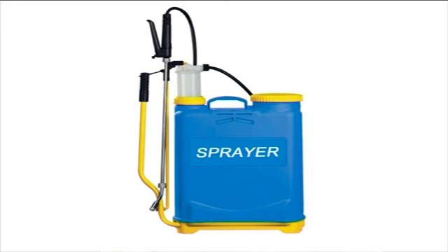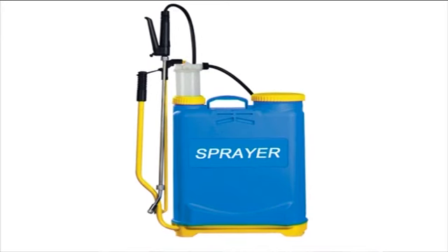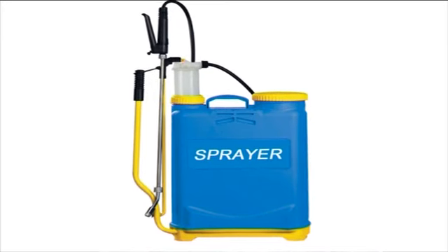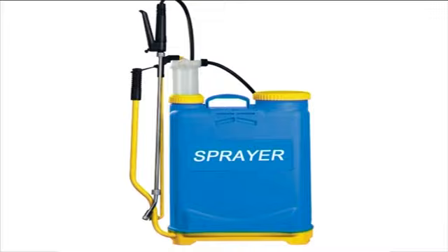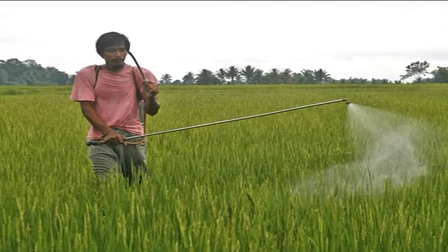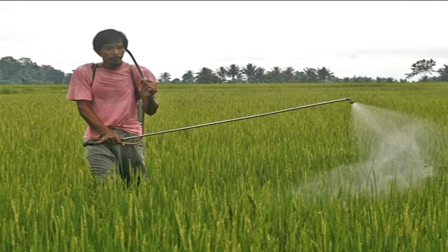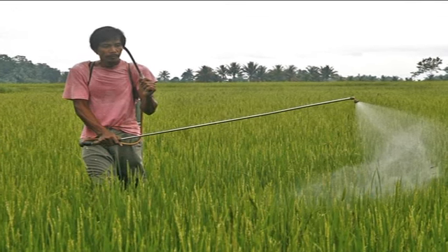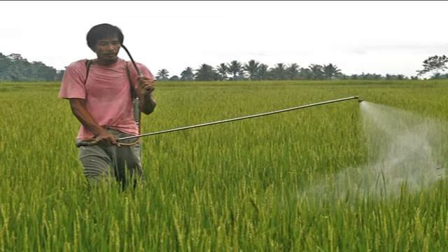Now moving on to sprayers. The sprayer is one which atomizes the spray fluid, which may be a suspension, an emulsion or a solution, into small droplets and ejects it with little force for distributing it properly. It also regulates the amount of pesticide to avoid excessive application that might prove wasteful or harmful.